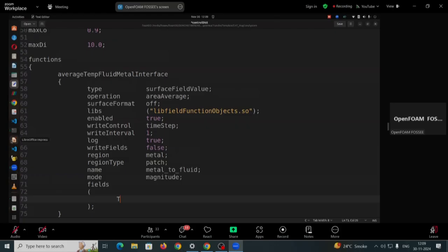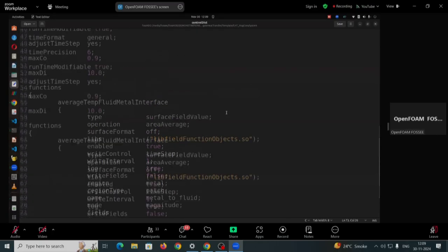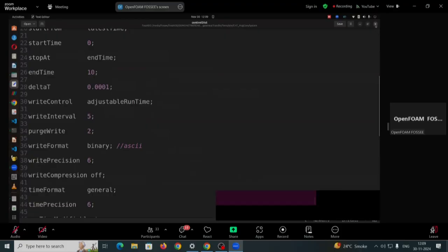You can use PyFoam as well. Depends, like there are many things. For some reason, in the CHT case, for us, the residuals are not working in this V9. Previously, it was working for us 6 months back. Suddenly, what has happened? I don't know. Some update or something. I'm not able to figure it out. It is not working only in the CHT case, but I have another case, which I will demonstrate, where I'm able to track the residuals and do the other things as well. So this is running. This was what I wanted to talk about for this specific case.